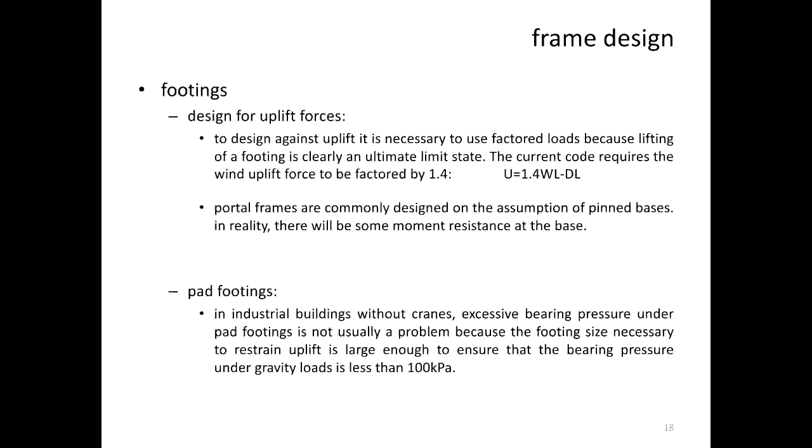Okay? So, of course, the footings generally, as it says there, which I've already explained, also provide weight as part of the uplift capacity of the building. Because the footings are very, very heavy. So what that means is you have your columns into the base plate, down to the footing, tie down.